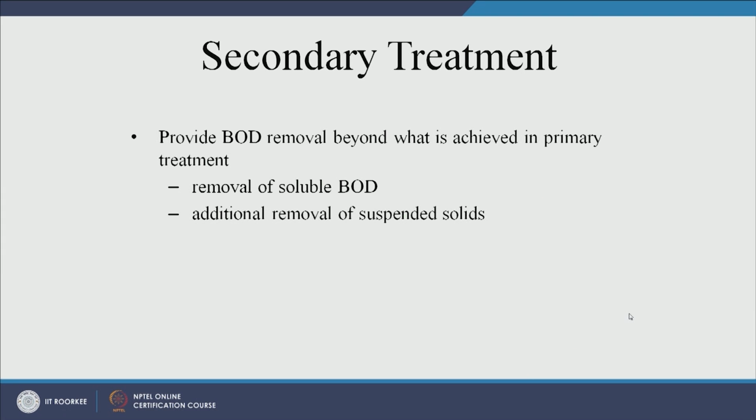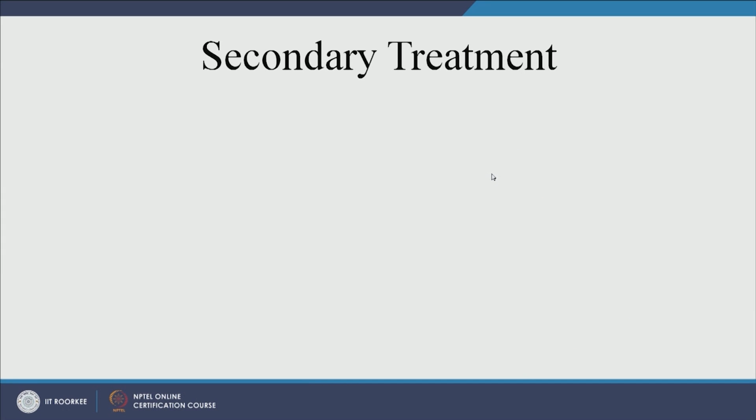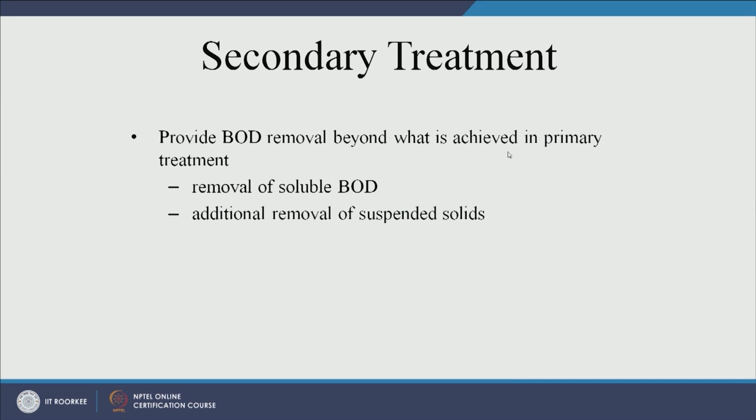Alrighty, so in secondary treatment, if you go back here, we are trying to remove BOD beyond what can be removed in primary treatment. In primary treatment, whatever could settle, the big particulate matter BOD, has been removed, but the soluble BOD remains. So this needs to be removed, and secondary treatment also removes suspended solids in the water.